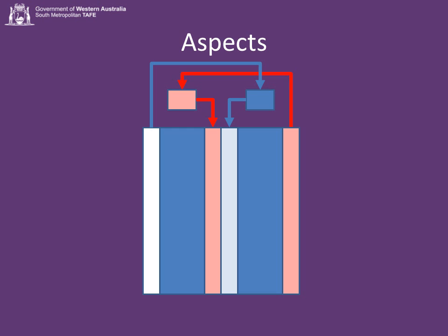How about this then? Instead of doing that, we simply move the air around. We take the air from the hot part of the building and we send it to the cold part, and we take the air from the cold part of the building and we send it to the hot part. It's very easy to do, just a few changes in ductwork. In many cases, this will mean that we don't actually have to actively condition any of the air. We take the air which is heated by the windows and we send it to the cold part of the building. We take the air which is cooled by the windows and we send that to the hot part of the building. This costs nothing.